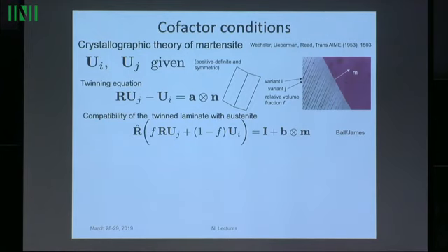And then there was a side issue, which is quite important: of course, the microstructure is not infinitely fine. So there's a competition between the interfacial energy on these boundaries and the bulk energy in this transition layer. If you include branching, the competition is a little different.